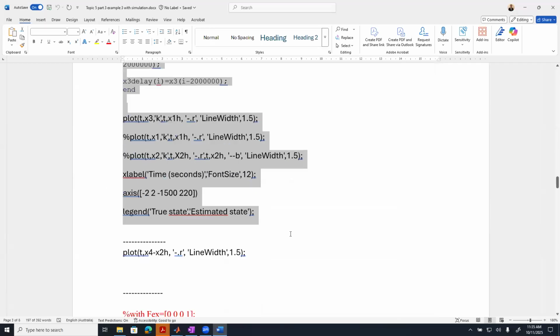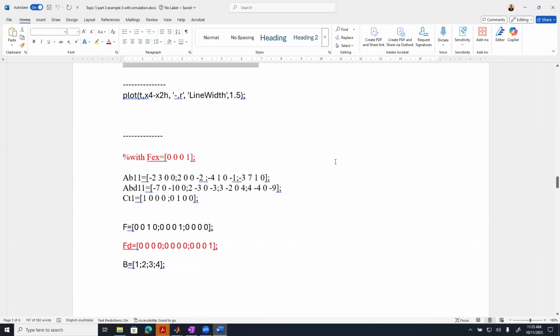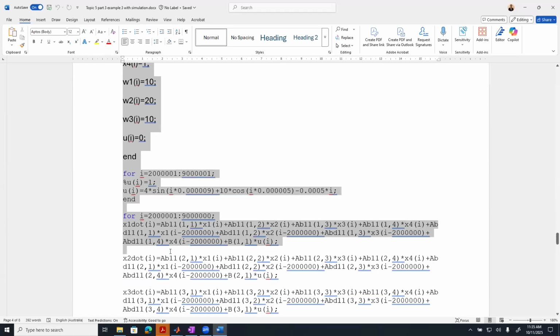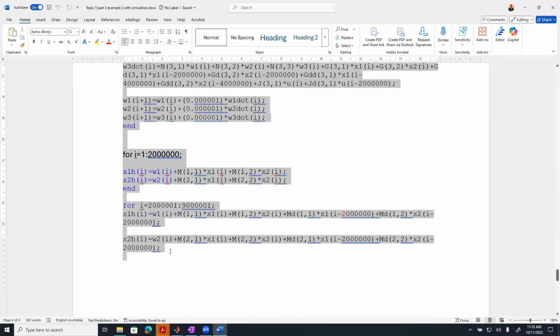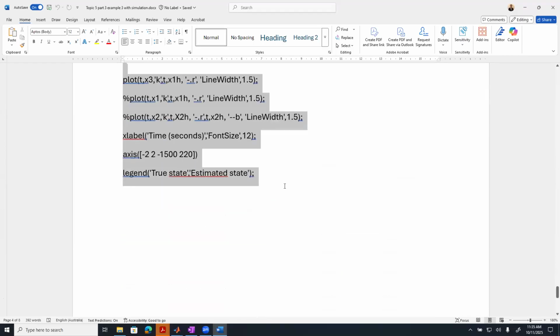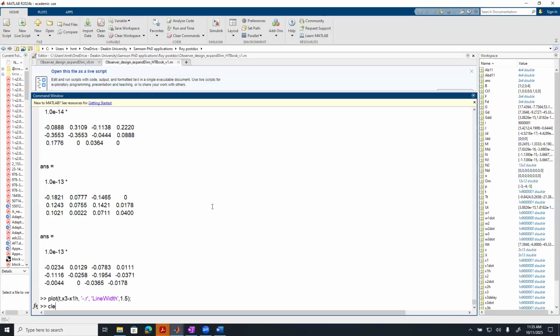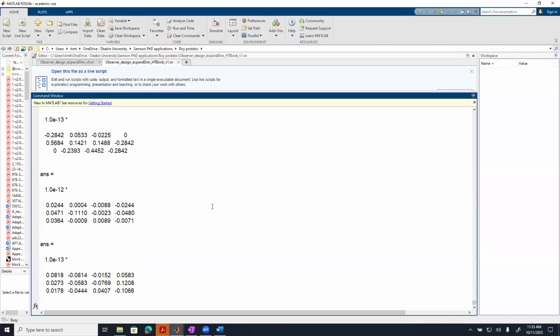So I don't know whether I actually have that. Yeah, this is the one where the extra functional is picked to be the last variable, the delay variable. And therefore, as you can see, all we do is just replace this FD by that. And then if we go through the whole process, the design, which is very systematic, the condition is satisfied, the pair is observable, and therefore we obtain a third order observer without internal delay using that alternative extra functional.